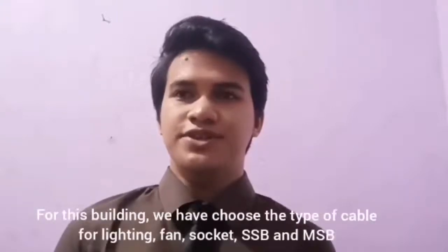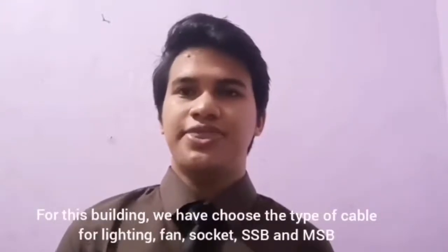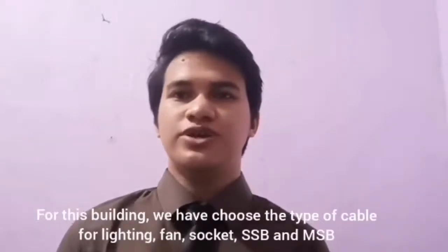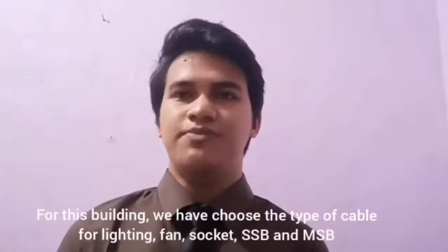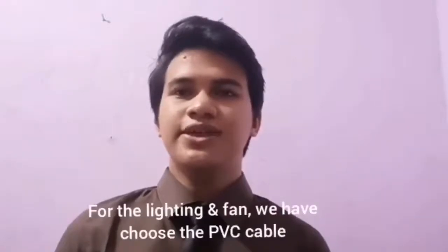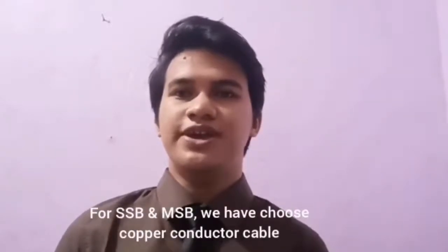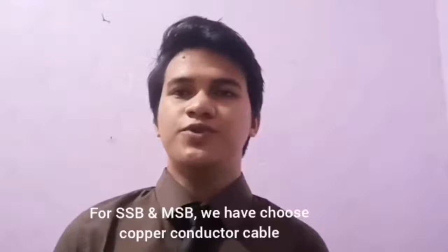For this building, we have chosen the type of cable for the lighting and fan, socket, SSB and MSB. For the lighting and fan, we have chosen the PVC cable. For the SSB and MSB, we have chosen the copper conductor cable.